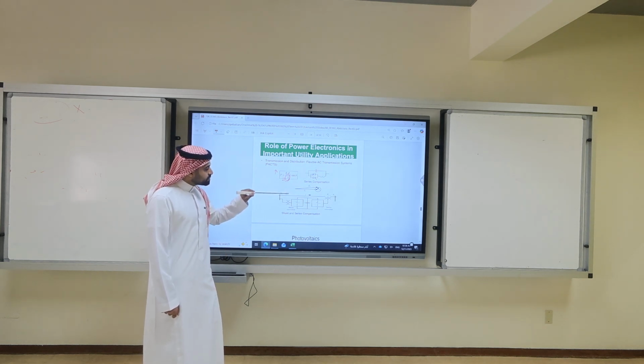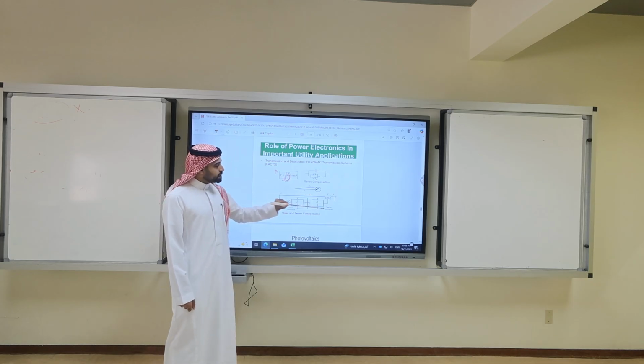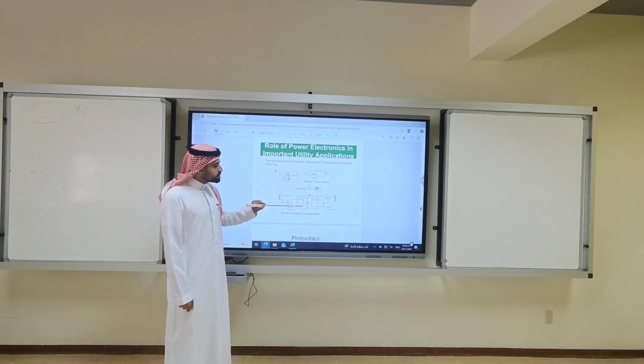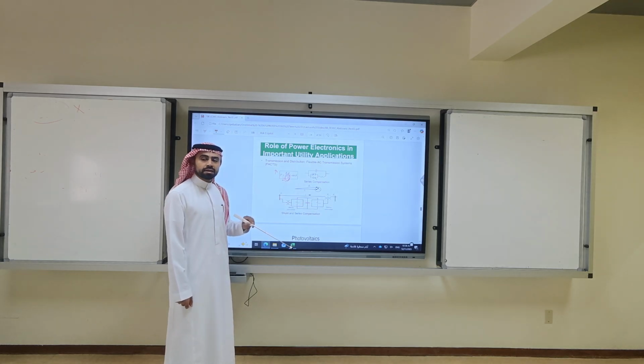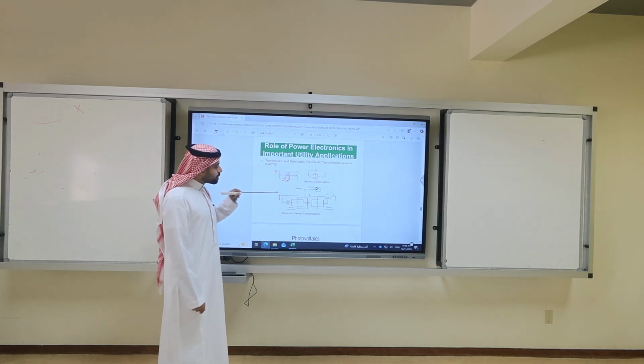Or if I have a transmission line, I add shunt converters, series converters, switched mode, to change the nature of the pi model of my system. Do you remember a pi model? With the T model? Yes. And they are a function of Z and Y, right? Yes. So if I add components in series or parallel, I can change the model of the line, then I can change the power flow.